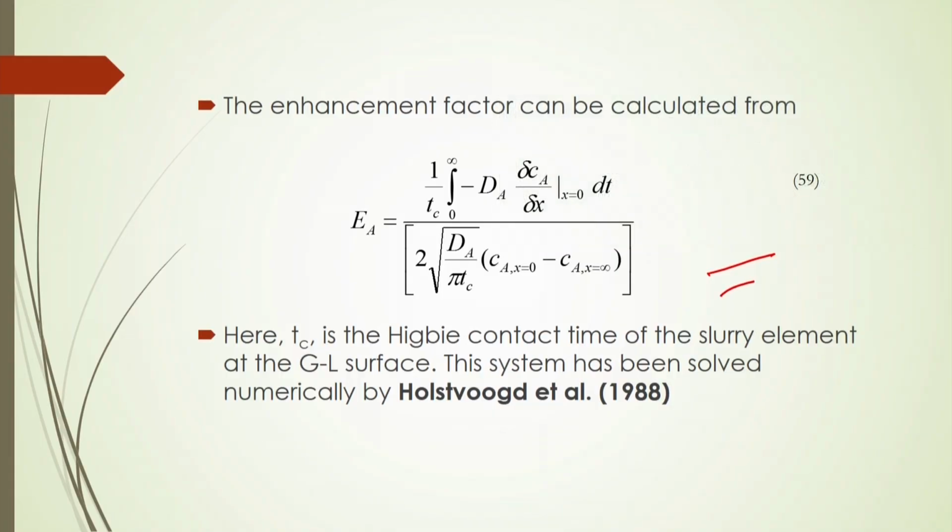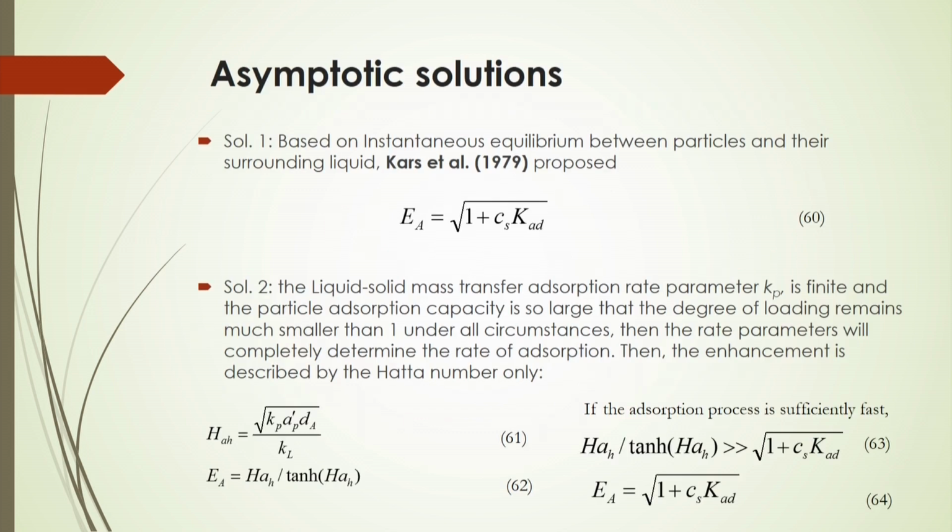In this case the contact time is the main governing factor, which will give you the degree of enhancement of the mass transfer inside the bed. This system has been solved numerically by Holst-Vogt et al., 1988, to calculate the enhancement factor based on this contact time and also the change of concentration within a very short film thickness.